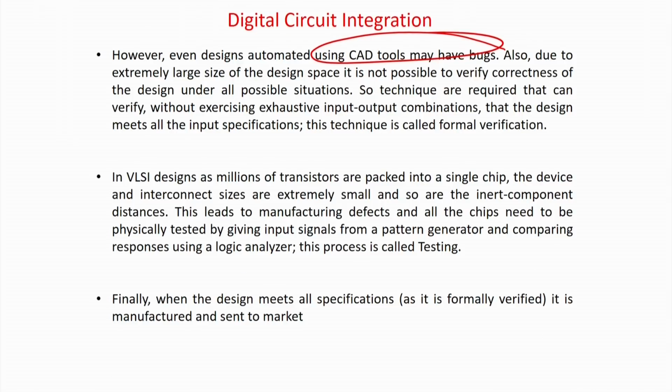So there is something called formal verification, because trying to check all possible input conditions is almost impossible. Think of a 128 bit adder. All possible input combinations will be 2 to the power 128 plus 128 plus 1 bit carry, an exponential problem. You can never solve that in a reasonable amount of time. So we have to check it formally. Formally means we have to have state based modeling, and mathematically verify that whatever input I have given as specification, the same thing has been implemented at the transistor level or at the gate level. At each intermediate translation stage, you have to verify it. So that is called verification. That is also a very important part of VLSI design.